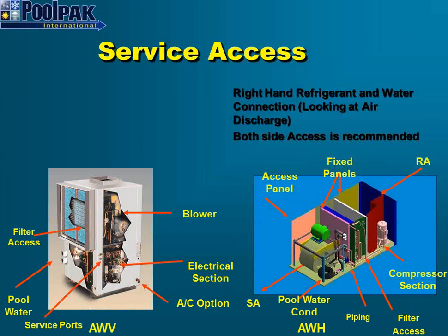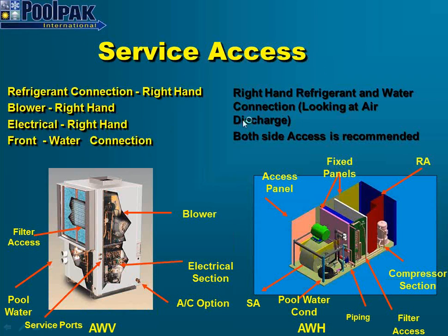Service access. It's good to have access from both sides. I've been in more than a few pool maintenance rooms over the past 3-4 months now, and it's usually pretty tight quarters. So it takes a little bit of imagination sometimes to create service clearances on both sides for the unit. You know, and depending on your airflow direction, you can make sure that the control panel, the access panels are on the correct side.